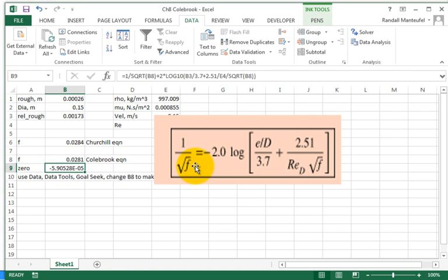All right, looks okay. So I'm sure that either in Wiley Plus they have something like the Churchill equation, or they're iterating with the Colebrook, or they only have so many sets of parameters, and then somebody went in and for each one of them hard-coded what the friction factor is for this Reynolds number and relative roughness. But the Churchill equation is not that hard to code up.